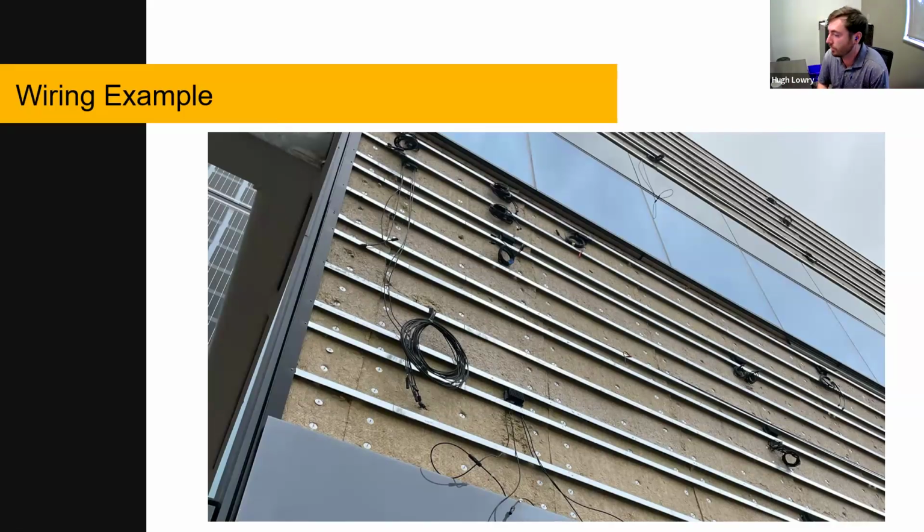But they also are how the panels are wired together. Each panel is wired into the optimizer, and then the optimizers are wired together back to the inverter. Without getting too technical here, it's important to note that these devices are important to the rapid shutdown solution, are mounted behind the panel itself in the air gap, and contain the wiring that's necessary to wire panel to panel.